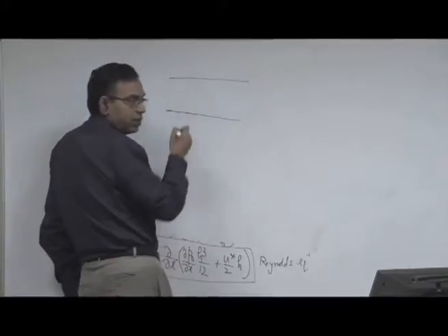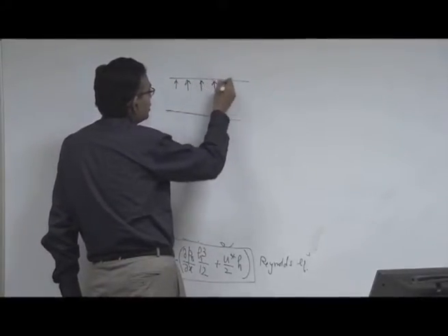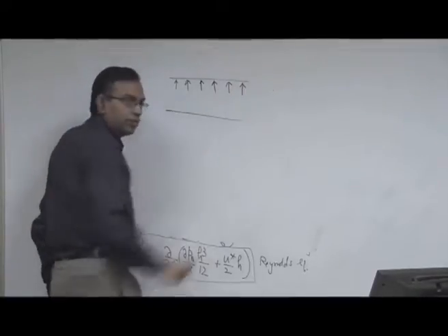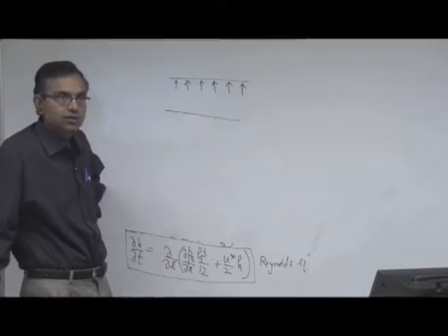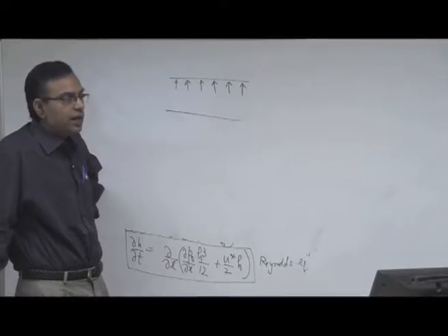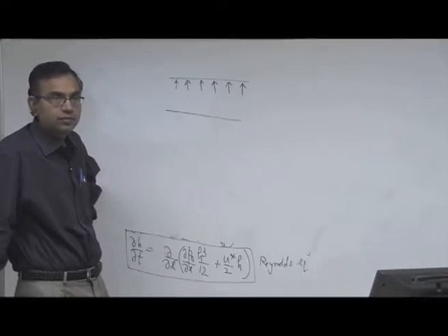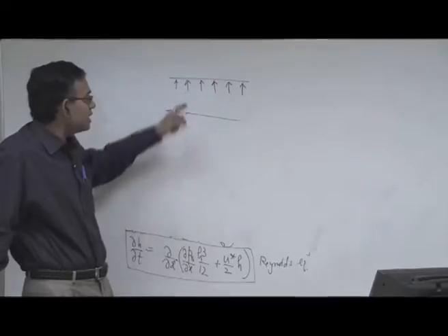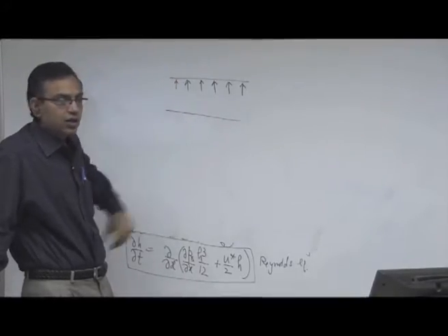So, pressure is positive. This means positive pressure, normal force onto the plate, inward normal force to be precise. So, it will require a huge amount of force to squeeze the two plates together, right, because there is a force that is trying to separate the two plates.